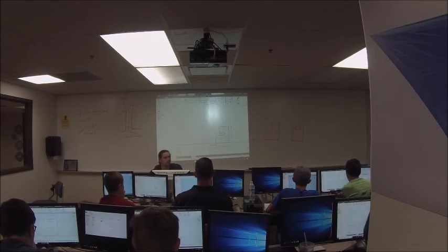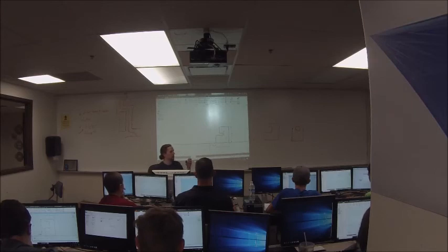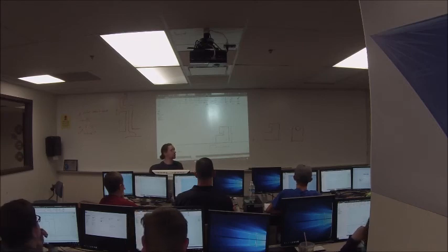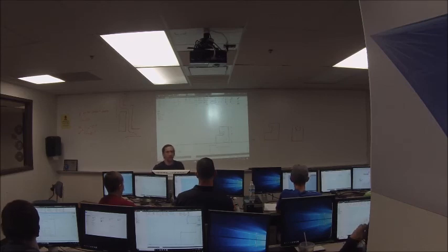And because this is a fairly complicated shape, there's a number of different ways that you can constrain it. When you're making a real part in the real world, you want to constrain it. You want to create the dimensions in the sketch that you care about in real life, right? If you're making a groove in a part, and you want the groove to be a certain width, dimension the groove to be the width you want it in Inventor. Don't dimension the positions of the two sides of the groove or something, right? Dimension in Inventor the way that you want it dimensioned in real life, in terms of the dimensions that you care about. And that'll just make it easier to go back and change the part later.